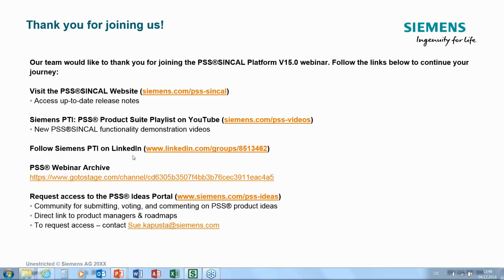So Sincal calculates the short circuit again in each step, and with this goes into the protection devices and checks the tripping times. Is this what you mean? Otherwise, we can get in contact again and have a look at it. So I guess yes, we do it, but maybe I did not understand it quite well.